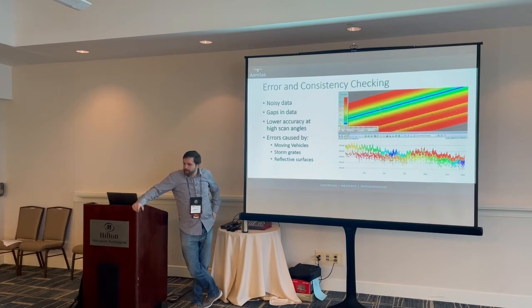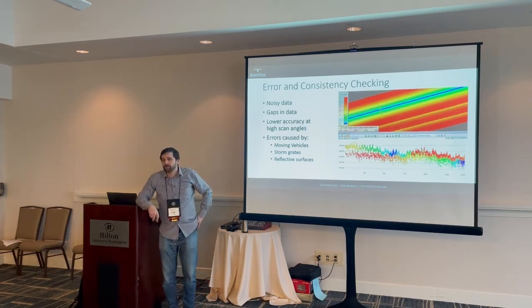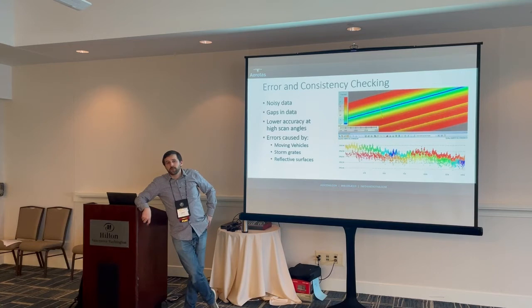This is kind of intriguing. I come to this whole thing from the world of hydrographic surveying, and we have patch tests that we run on any multi-beam swath we run, and the errors are exactly what you're showing there. But we have certain protocols in place before we start surveying to cancel that out and nullify that by running in different directions and at different speeds and that sort of thing. And then we get our roll and our biases negated that way. Is there anything like that in the system, or is it all as a post-process? Is there anything that the machine does that's the equivalent to a patch test like that?